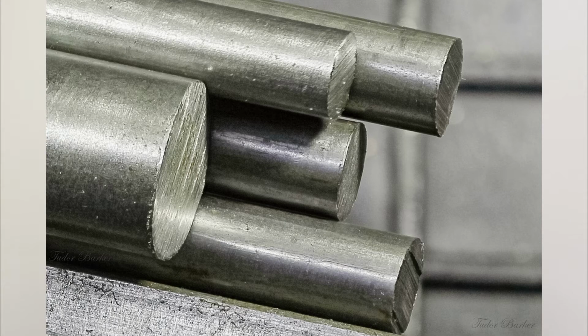So bar is definitely the most customizable type of steel. Bar steel consists of round bar, square bar, rectangular, and hexagonal. Now bar steel is specified with an alloy number, which is a 4-digit number. The 4 digits are then separated into two 2-digit groups. The first 2 being the alloy number, and the second 2 being the carbon content.